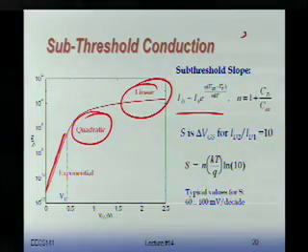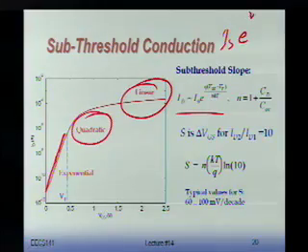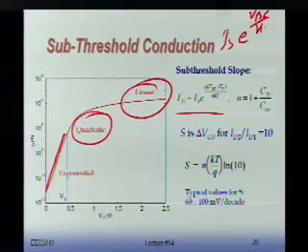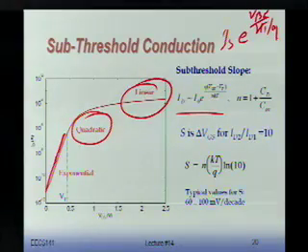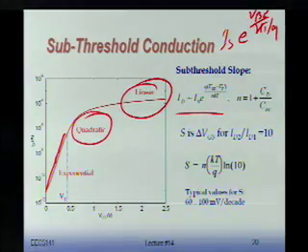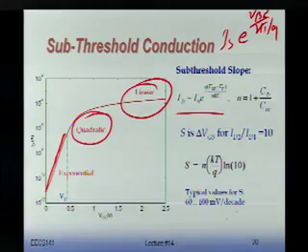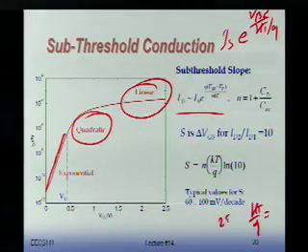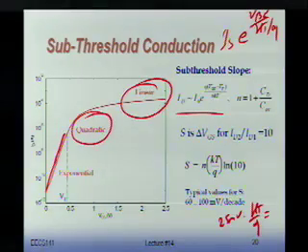In the bipolar case, you're going to have IS times e to the VBE over kT over q, for those of you who remember that. Same equation here. ID is proportional to I0 times e to the (VGS minus VT) over kT over q. And kT over q we call the thermal voltage. It is approximately equal to 25 millivolt at room temperature.